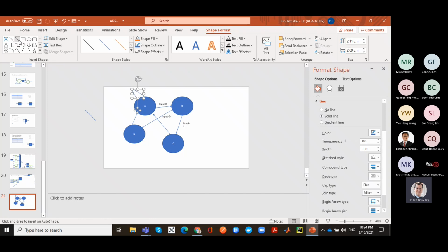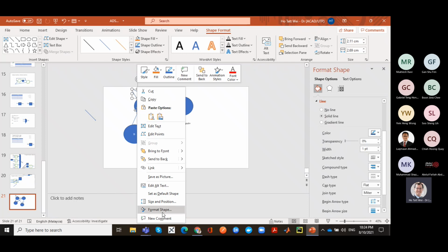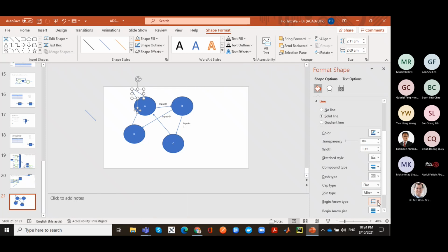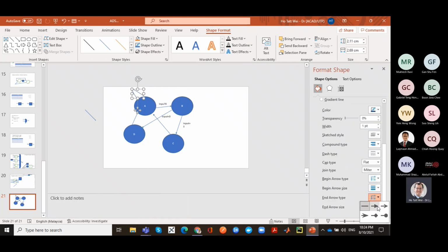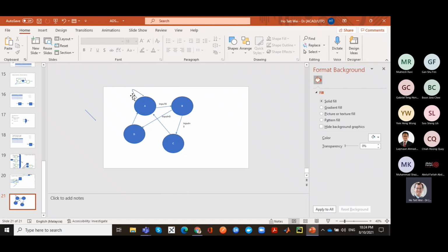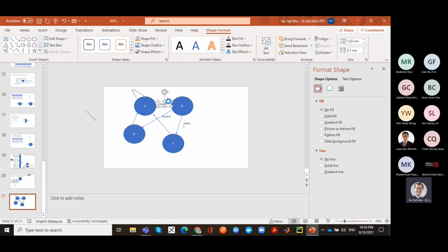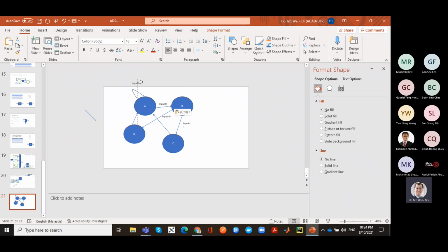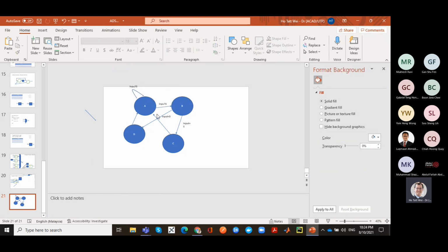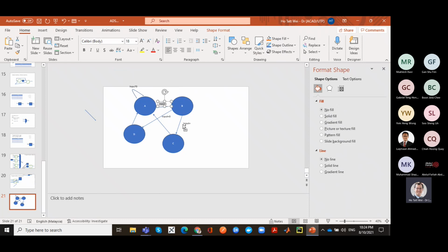What I'm saying is that in most cases, the most useful state transitions tend to be of the form where if the processing or the computation isn't finished, you continue to remain in the state at subsequent clock cycles. So when the input is 0, you remain in the state. But when there's suddenly some condition, say the condition is 1, is true, then you transition to the next mode.